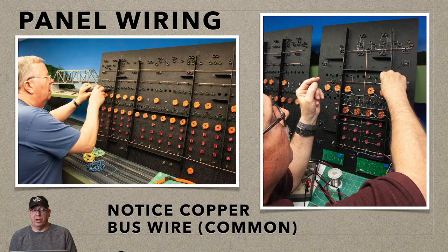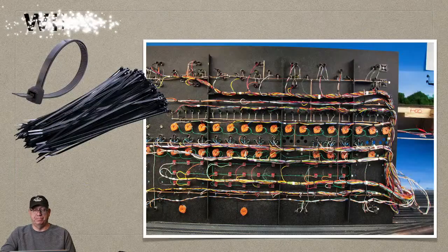On the right-hand panel, John DePaw. John is from Michigan, and John came down and with Bill Carr and worked on the panel. And you can see we're tying, basically just like an automobile, half of all the electrical components to a ground. That way we only run half the wiring into the panel, because half of all the light emitting diodes, switches, everything goes to a ground, and then we run one other lead in to illuminate or register how turnouts or switches or rotaries are set. So that's what they're doing there.